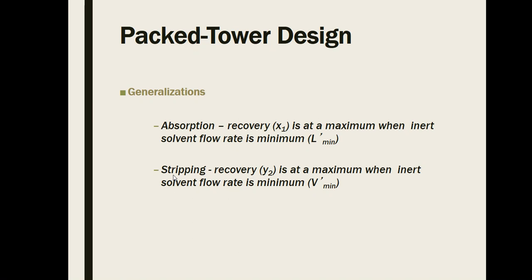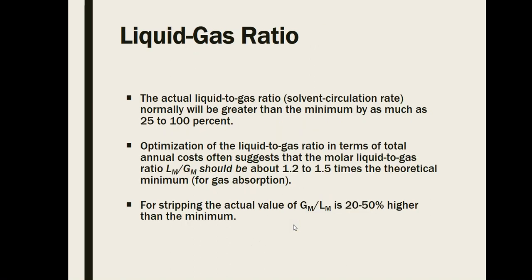Correspondingly, we apply the same principle for stripping. So recovery Y2 is at the maximum when inert solvent flow rate is a minimum. This time we are determining V prime minimum, not L prime minimum, because our solvent in stripping is the vapor phase, not the liquid phase.